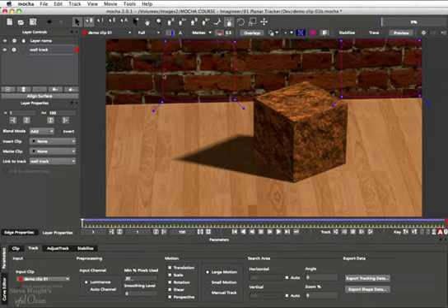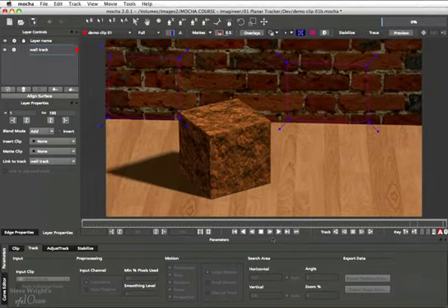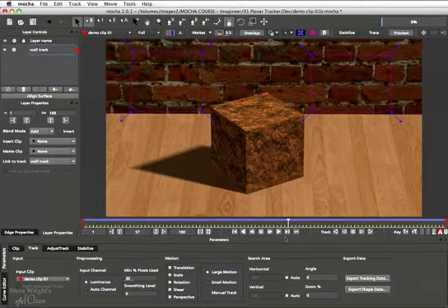This one was drawn with the Create X-Spline Layer tool, which created the new layer. The second one was drawn with this, the Add X-Spline to Layer tool, which put it in the same layer as the first one. So as I turn that layer on and off, you can see that both splines are toggling on and off. I've already tracked them, so we have a very nice track, and now we're ready to actually use this. So this is another example of putting more than one spline in a layer.